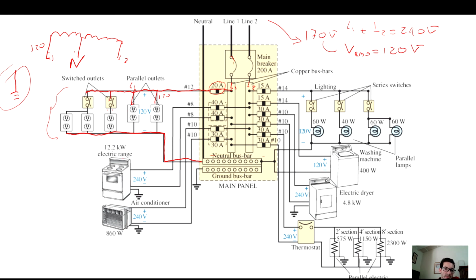Now, if you notice, let's say they tell us that this appliance is electrothermal, because it's turning electricity into temperature, into thermal energy. This oven is operating at 240 volts. So what they do is that they take L2, of course there's a fuse, and now the amperage is higher because it can go up to 12,000 watts. So they're saying, okay, there's going to be L2 and L1. Notice L1 and L2, and then we're going to connect to ground. This is part of the plug, but this will eventually go to all the grounds in your house that are connected to a rod outside of your house somewhere.